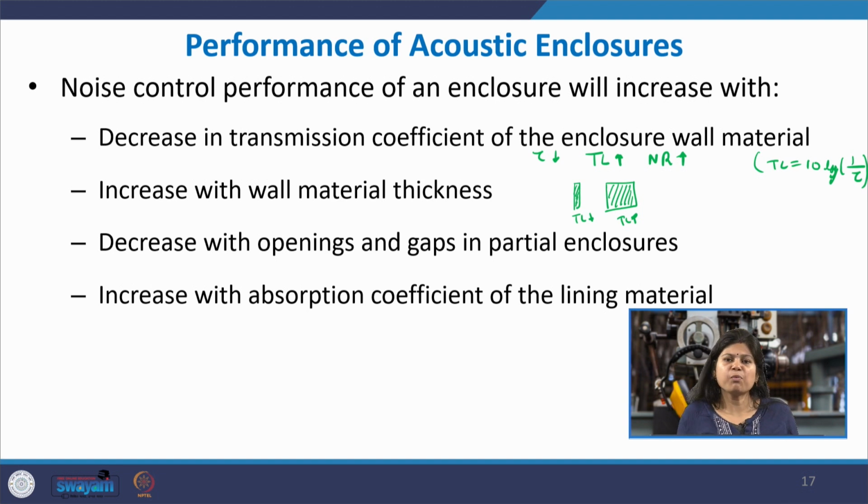They will most importantly create some alternate pathways that the sound waves can take and reach out. So, the purpose of the enclosure will not be served, because the name itself suggests enclosure. It is about enclosing the source or the personnel completely, completely encapsulating them, and with any gaps or openings, that purpose is not served, because the sound waves will now get some pathways to go ahead and pass through these enclosures.